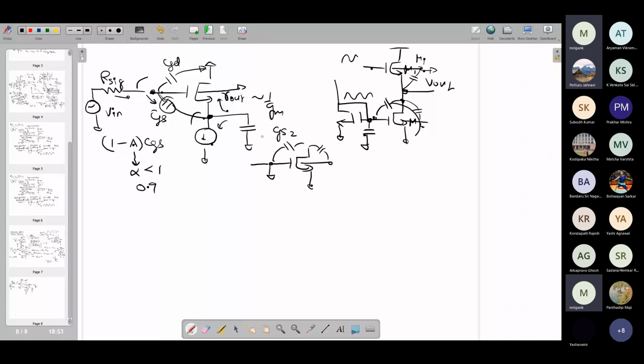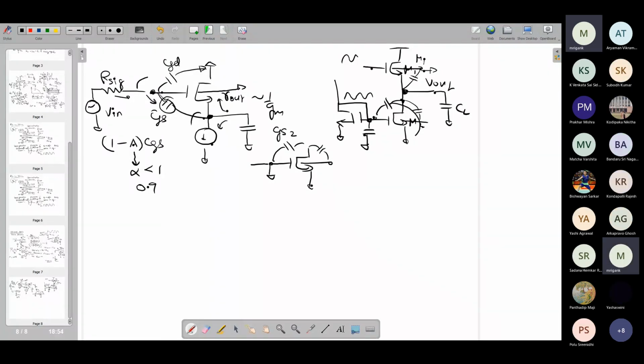If it is not, then these are the dominant capacitances. These are the contributors, and then whatever input capacitance you may have, you should include it. Whatever the C load of the next stage, small or big, you need to include that. And then that multiplied by the overall small signal resistance here, which is 1 upon GM, gives you the net pole, the RC time constant at this point.